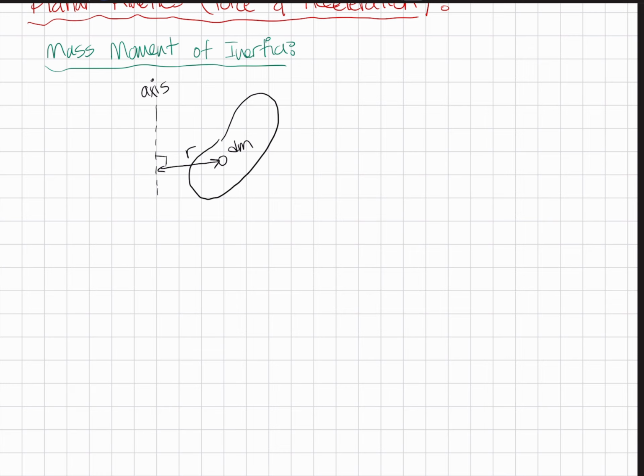And so with this schematic in mind, we could set the definition of mass moment of inertia as I equal to the integral of r squared dm, and typically this ends up having units of kilogram meter squared. And of course, if we want to be even more mathematical, we could say we're integrating over the entire volume. So this is the entire volume that we're considering.